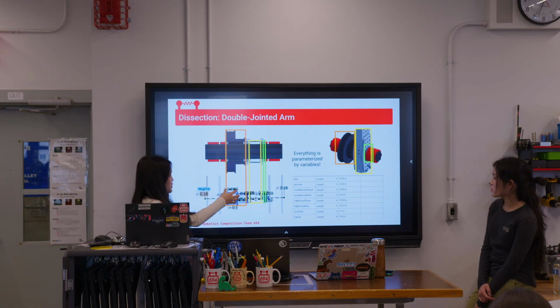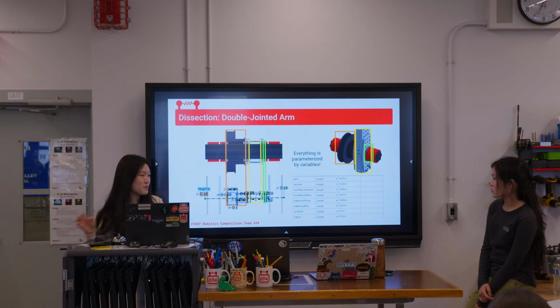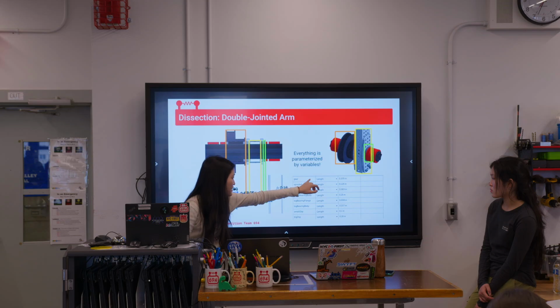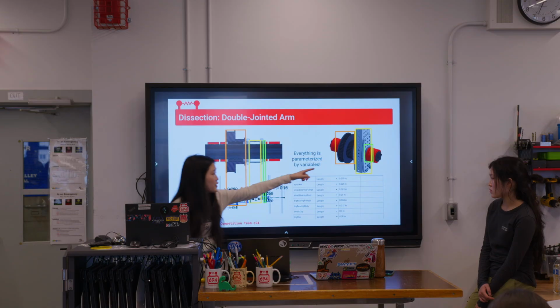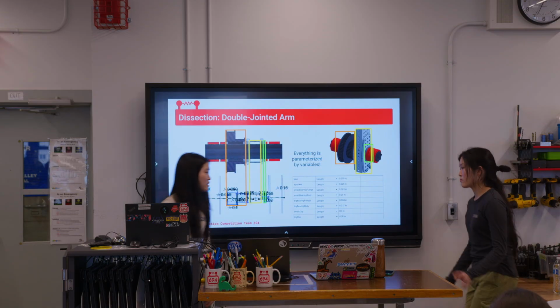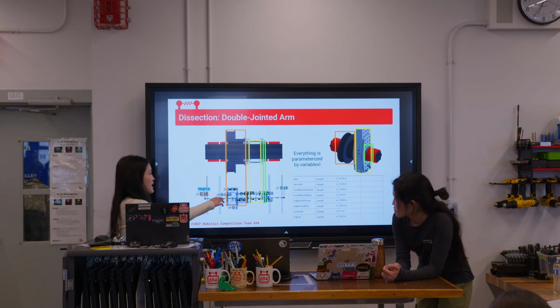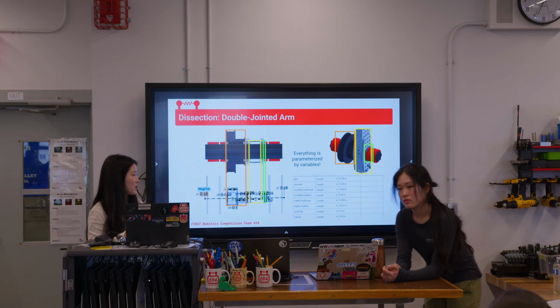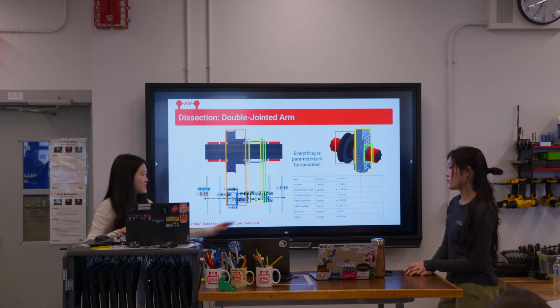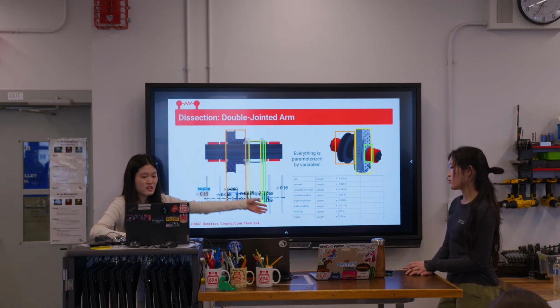And you may be thinking it's kind of annoying typing out all the values for the bearing flange thickness and everything. You don't have to do that because most of these are parametric, so you already have a variable for that. You have the thickness of a gear, the thickness of a sprocket. You can name whatever you want, but I name mine small bearing flange, because the smaller bearings, and I also use bigger bearings, like the ones for the Spline XL. So you would have all these parametric variables, so you don't even have to type all these specific decimal points. If you see fx here, that means it's a variable. So if I know I have a pulley here, I can just type the variable out, and everything will be really, really fast. It doesn't take too long because you already have the parametric variables.